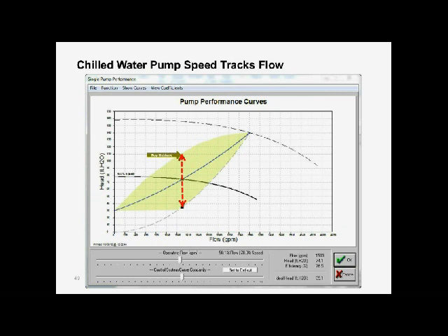So if I'm at 70% load on one coil, I'm at 70% load on all coils. But that's not real. If the coils that are far away from the plant are the most active, the highest loaded, and the ones closer are not, I'm going to be operating up here in the head area. If the coils that are close to the plant are more active, then I'm going to be in the lower part of the area.